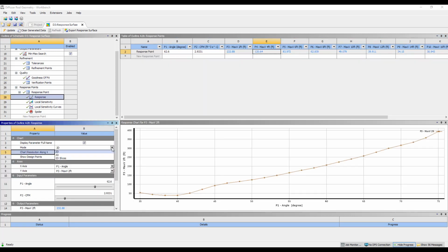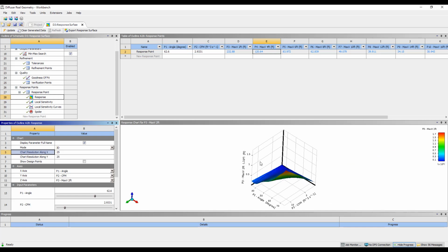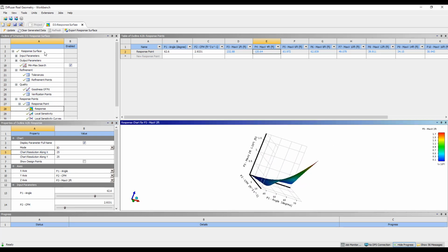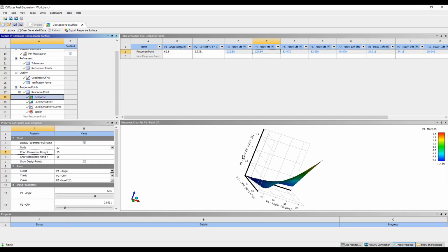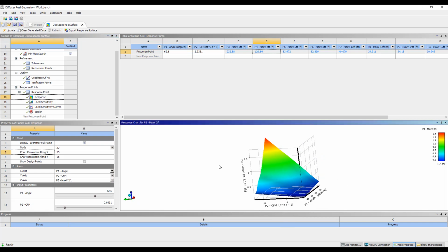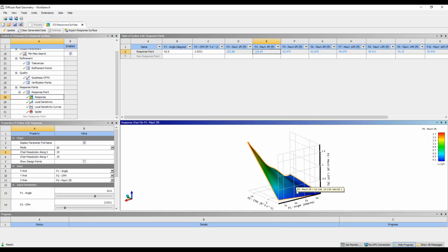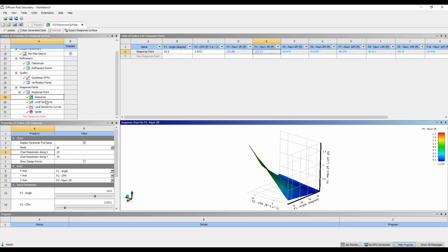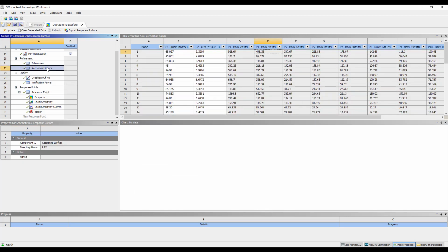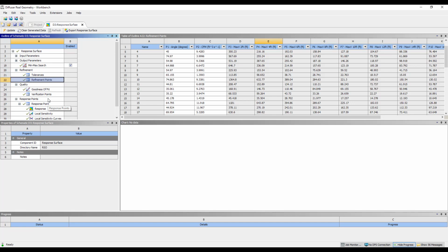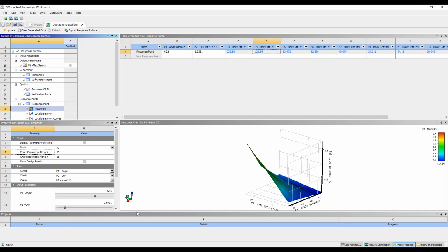From that data, Ansys is able to create an interpolation function using a variety of methods. I'm using a genetic aggregation, so it's using 4 or 5 different interpolation methods, trying to interpolate between all of that data and coming up with a curve that looks like this. We can look at the fitting. It is good because I fit the data to that. I've put the verification points into refinement points to update my response surface. I should probably do some more verification points and see how that matches up with the predicted data, but this is probably sufficient for our purposes.